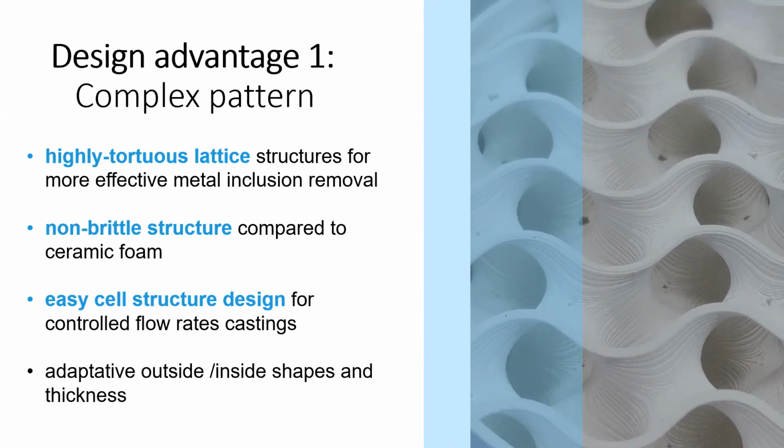Basically, you put the part in a rotary tumbler with some abrasive materials, and you just let it stay in that media for quite some time, and this will polish your part to a very nice level of surface finish. Of course, the drawback is that you polish all of the part, so you can't keep any very sharp angle if you do tribofinishing. But apart from that, this really works well with both ceramic and metal. Okay, thank you.